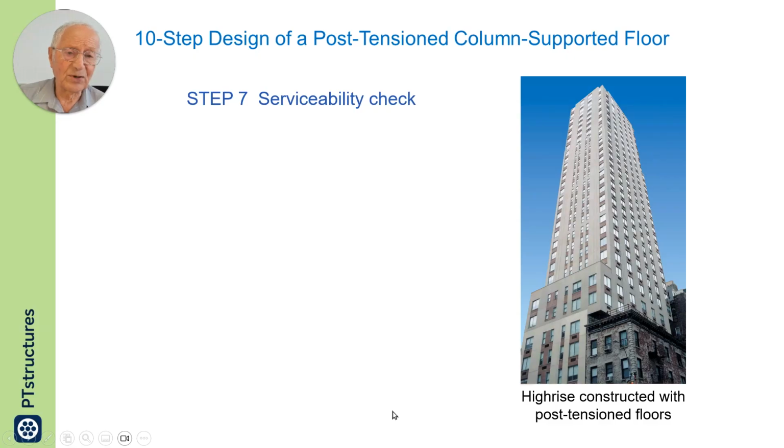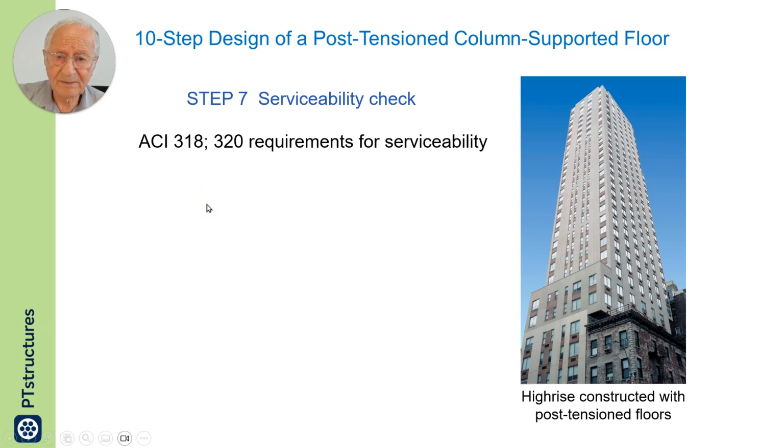Next, I'm going to do service check. I calculated the actions from post-tensioning. I have calculated the actions for dead and live. Now I do service check. That is step number 7. For service check, we have to do stress check. We start with stress check.